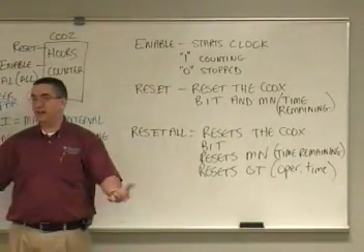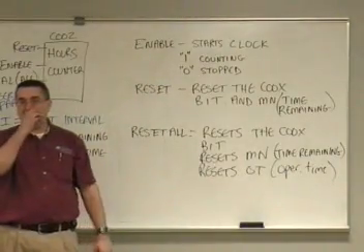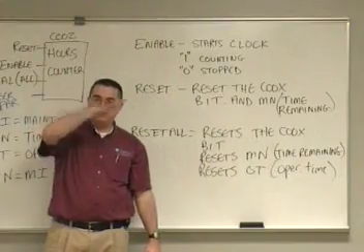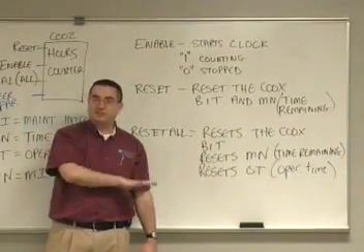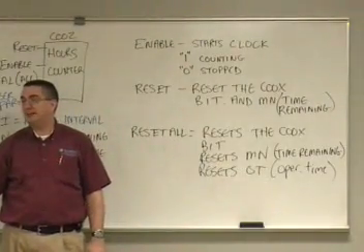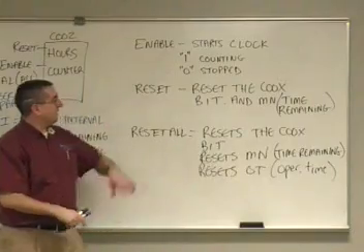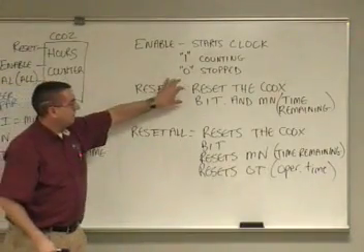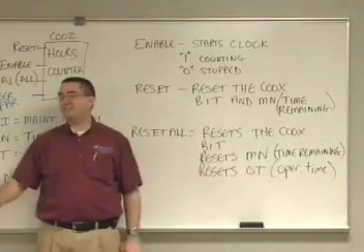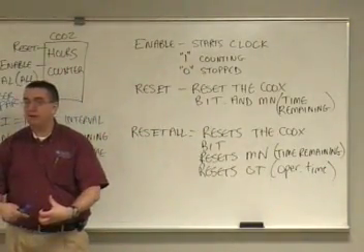If it was 3,000 hours, let's say I start up and I start counting down from 3,000 hours on MN, 2,999 all the way down to 1 hour. When I get down to 0 hours on MN, the C00X bit will energize. If I hit the reset pin, then my C00 bit will de-energize and MN will go back to the maintenance interval value, 3,000 hours. So I'm back to where I'm running.